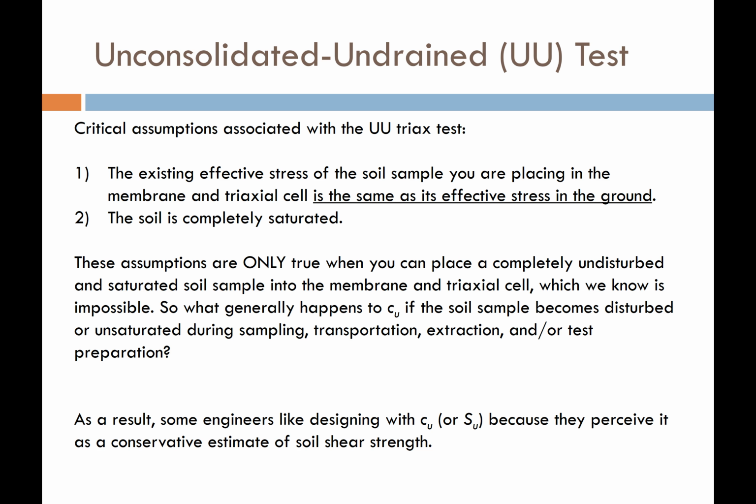The second assumption is that the soil is completely saturated. Now, these two assumptions are only true if we can retrieve and place a completely undisturbed and saturated soil sample into the membrane and triaxial device.